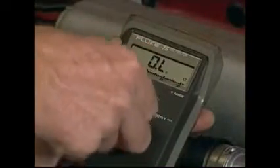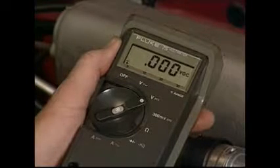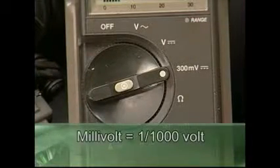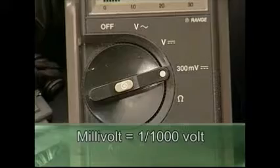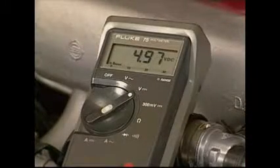The voltmeter function of the digital multimeter can be selected by rotating the selector knob to the V on the dial. Some multimeters will have a second option for testing voltage, that of a test in millivolts or thousandths of a volt. That can be used to check voltage in low-voltage electronic circuits. For most automotive tests, select the V function of the multimeter.